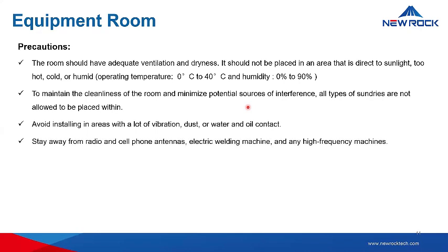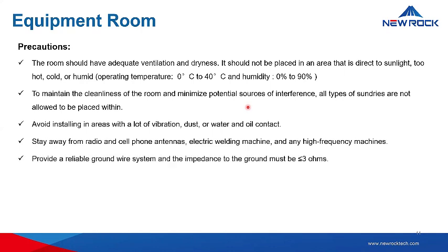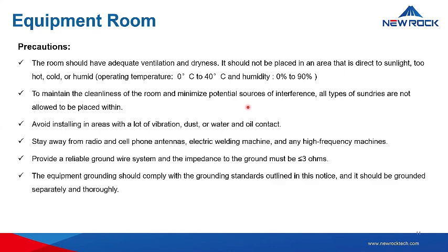Then we need to stay away from radio or cell phone antennas, electric welding machines, and any high frequency machines. Next, we need to provide a reliable ground wire system, and the impedance to the ground must be less than or equal to 3 ohms. The equipment grounding should comply with the grounding standards outlined in this notice and it should be grounded separately and thoroughly. So it is very necessary that you use the ground terminal in our equipment and use a suitable grounding system for the equipment.